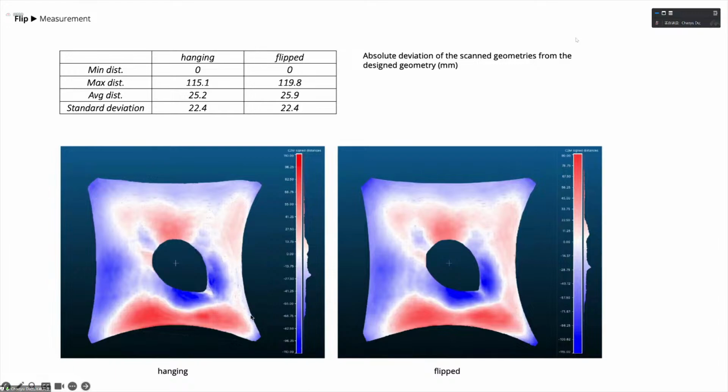And the largest deviation happens along the support in the middle and around the singularities, which you see here, where there are a lot of unique tiles. And we can already see, in the hanging stage, that this part is not very smooth compared with the other part. And we think that these errors can be caused by the manufacturing accuracy of the knitted fabric, the slackness of the boundary cables, and the complexity of the unique tiles, considering that a small number of tiles are not CNC cut, but cut by the students on the site.